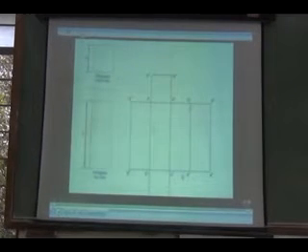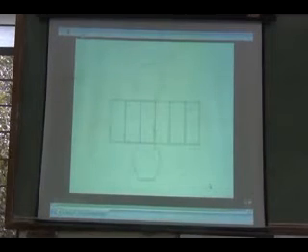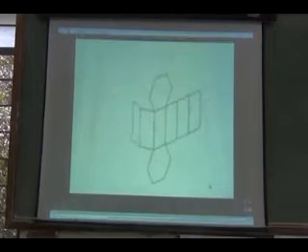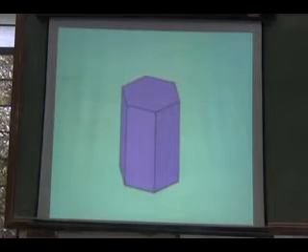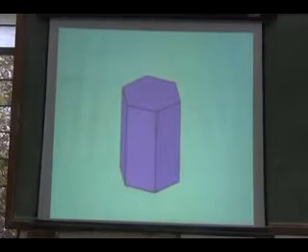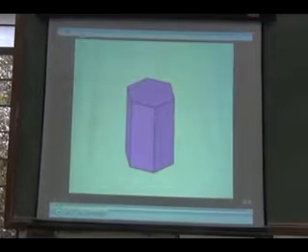Development, 4 times its base size. So what is the length? I am asking you. 4 times its base size, right? What will be the height of that one? Same height, right? So that is similar to that. The hexagonal prism will have 6 times its base side and the height. Okay, that forms the rectangle. So just by folding, I can obtain the required solid.